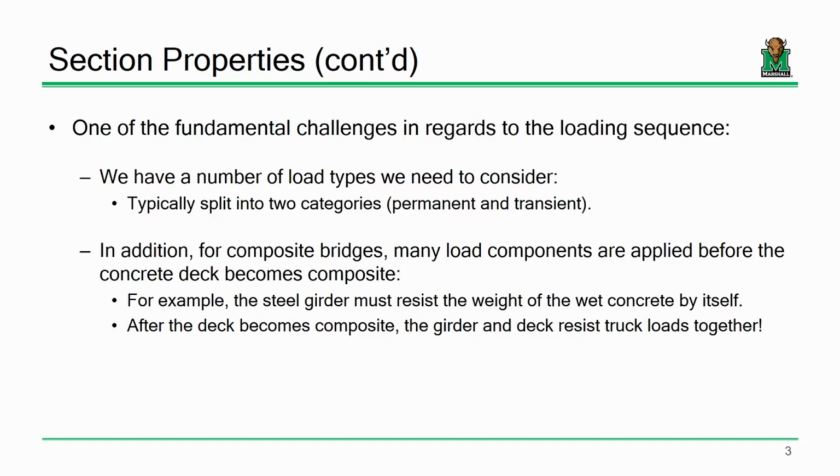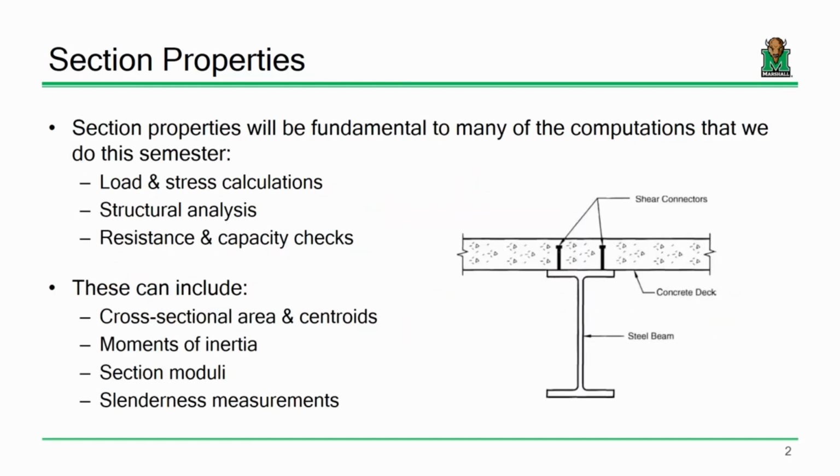All the permanent loads on the structure, that's a category in and of itself. The other category are the transient loads: the vehicular traffic, dynamic impact, if we're going to consider any seismic effects or anything like that. Stuff that's not always on the bridge, stuff that moves. Okay? What makes bridges unique, and specifically the case when you're dealing with a composite structure, something like this, is